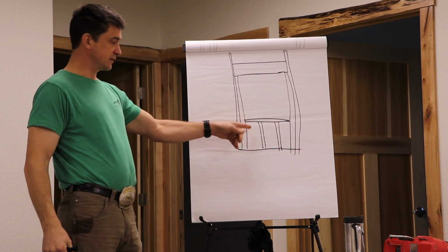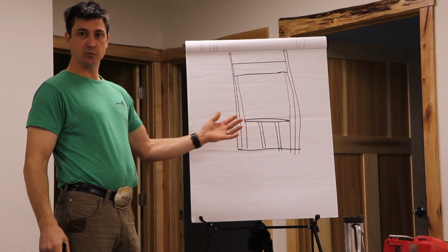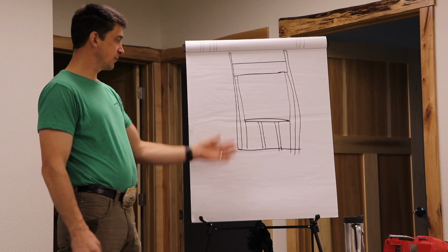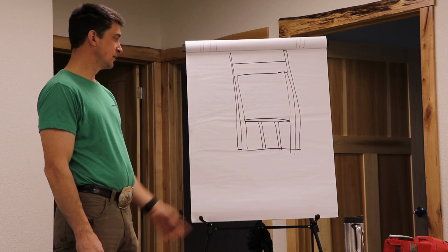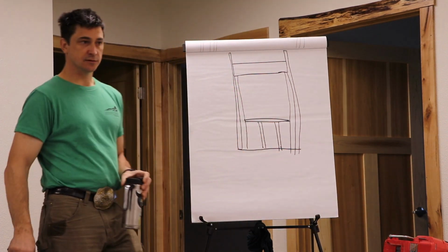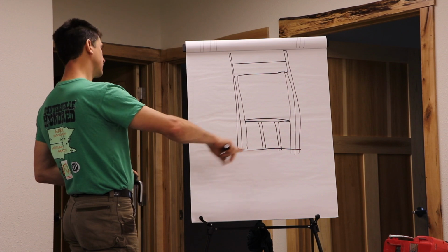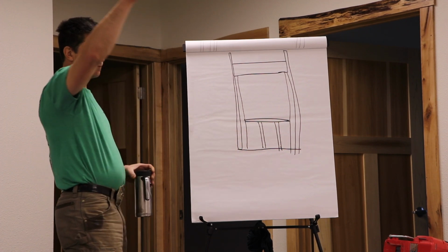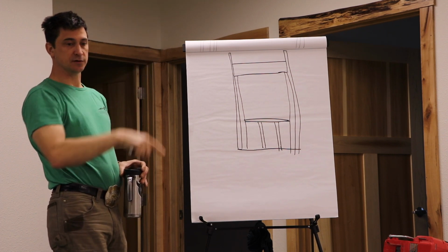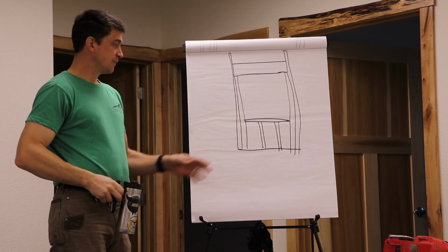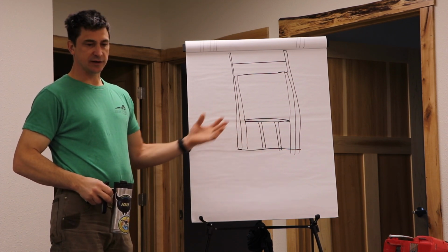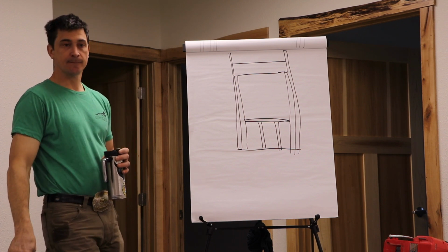This, one, it saves you some lumber, it saves you time when you're framing, and it saves your electrician a ton of work. Your electrician will come in here and be like, oh, this is awesome, because he can blast a drill bit through 2 stubs in like 5 seconds, instead of having to drill through the floor and then crawl down the crawl space, 50 feet into the crawl space to drill through 3 joists and then up, and then he's got to go up there and run his wire through that. Like, by putting a ton of framing in here, we multiplied his work to get 1 wire in there by like 10-fold.